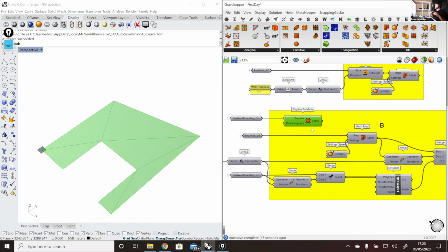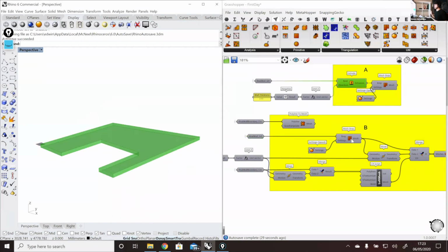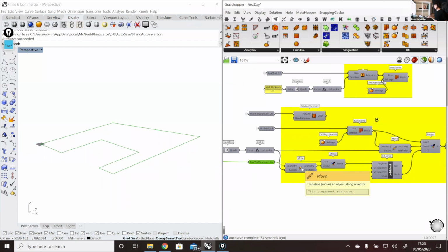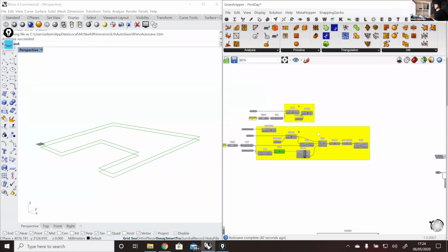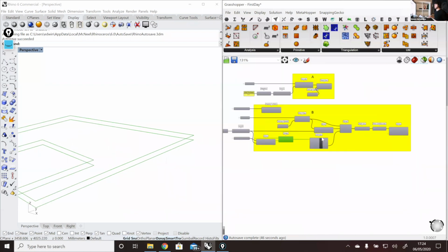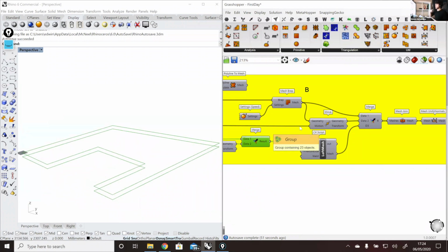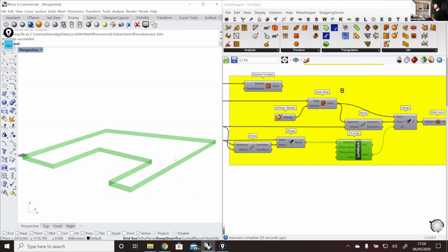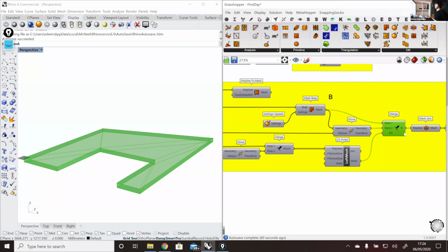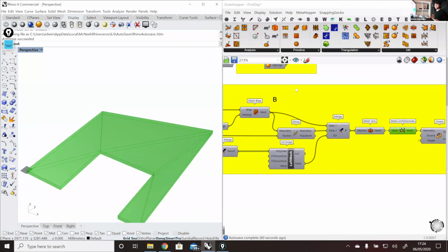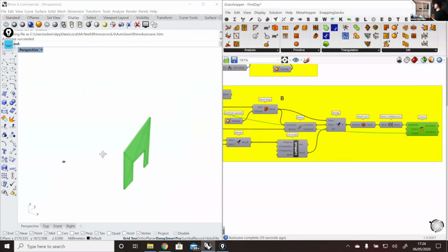However, if you have a window or a geometry inside this geometry, then I'm going to use the mesh BWrap component. But I'm not meshing all of this solid, I'm just meshing one of the faces. Then I use this boundary, moving it in the Z direction by the same wall thickness. With that I have my two polylines, a list of polylines, the same that we had here. With this list of polylines, I use the loft mesh component that we also used in the other example, and with that I create my sides without going through a BWrap. Then I can move this down, put my sides, and I've created my mesh from scratch without ever going through a BWrap. When I position this, I have my wall positioned as a mesh, ready to be rendered by the online viewer.